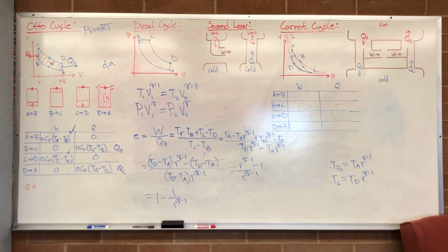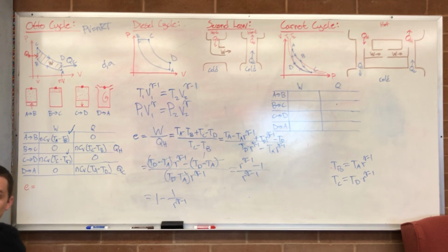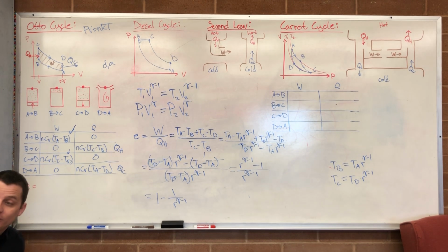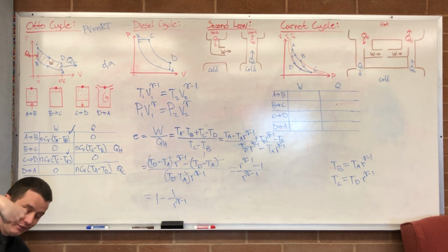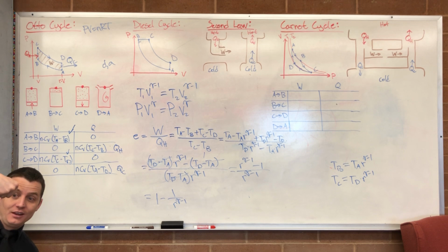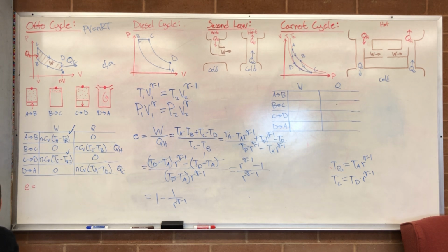All right, so that's an actual question. Here's the problem. As you compress a gas, what happens to the gas? Heats up. The temperature increases. And as you increase the temperature, the gasoline in there can suddenly just ignite. Because it's so hot? Yes. So what you could have is, as your piston is compressing, the gas just ignites and pushes your piston back before it could even finish its job. Oh, so it's not even going to start hitting the spark. Yeah, so the spark plug won't even be used. You're just going to compress it so hard that the gasoline just ignites.